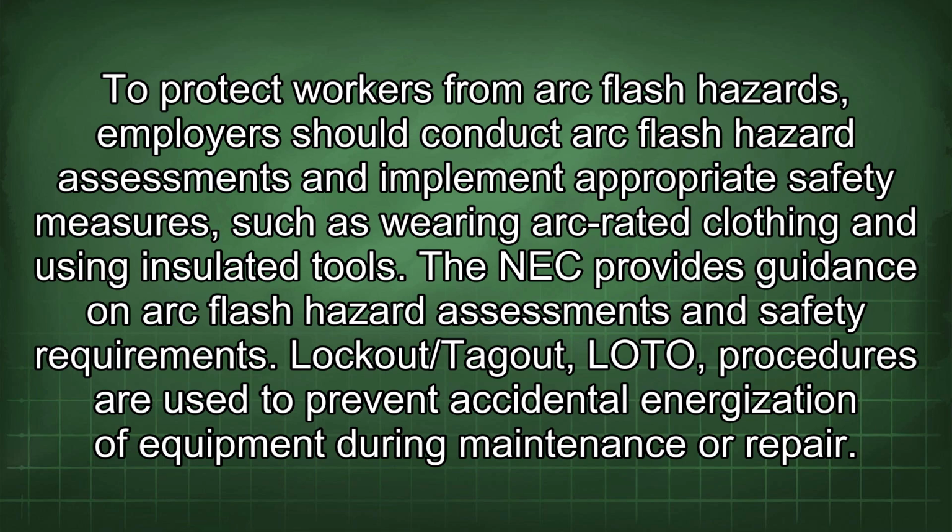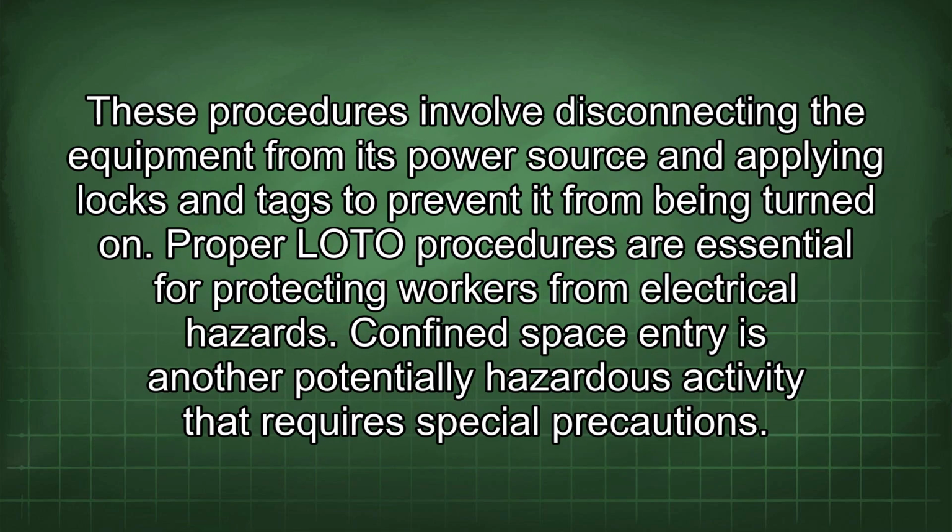Lockout/tagout (LOTO) procedures are used to prevent accidental energization of equipment during maintenance or repair. These procedures involve disconnecting the equipment from its power source and applying locks and tags to prevent it from being turned on. Proper LOTO procedures are essential for protecting workers from electrical hazards.